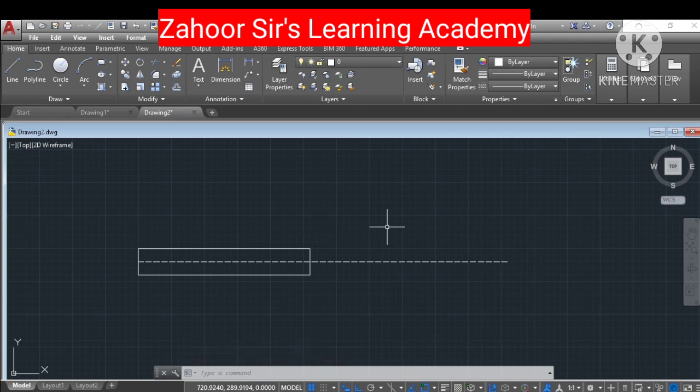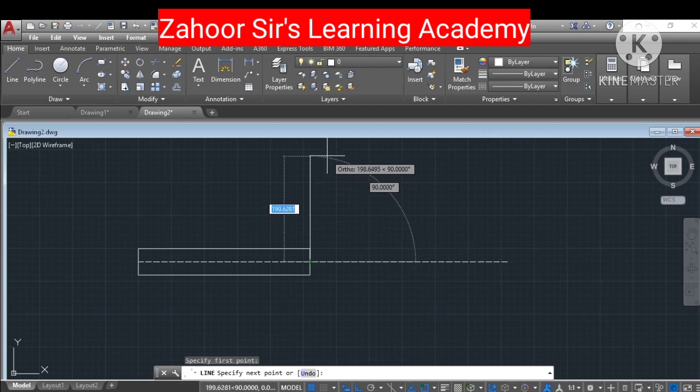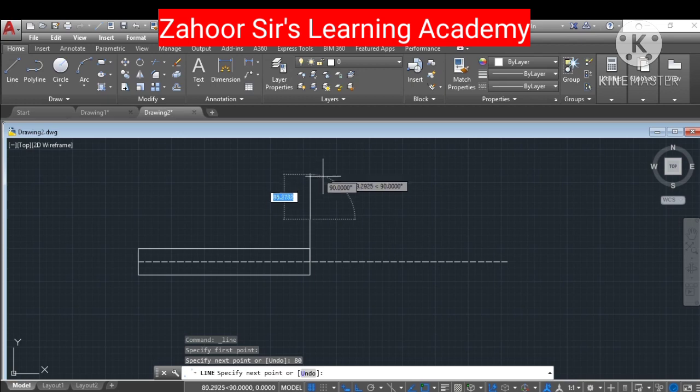Now, as I said, the coupling comprises the disc. After drawing the shaft, I will draw the middle disc portion. The diameter of that disc is 160 mm and the width of that disc is 30 mm. For that, I will again go to the line command and draw a line from the center point upwards. I will click here, then go up 80 mm, write 80 mm, then press enter.